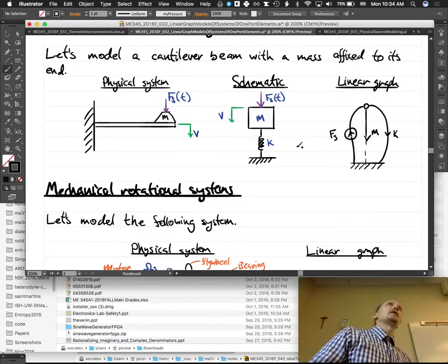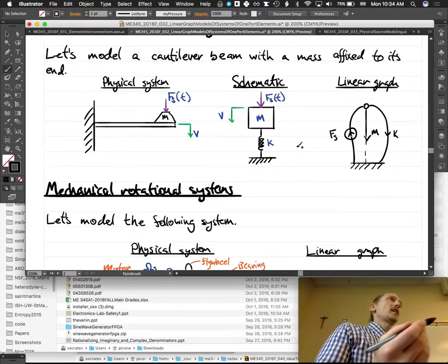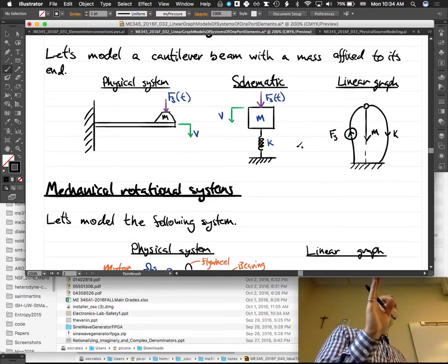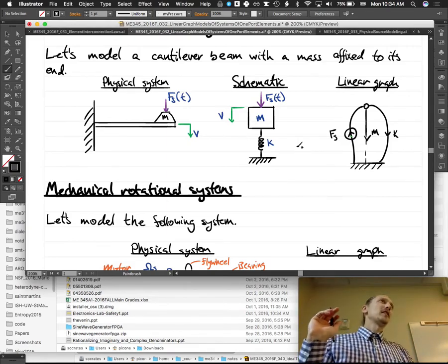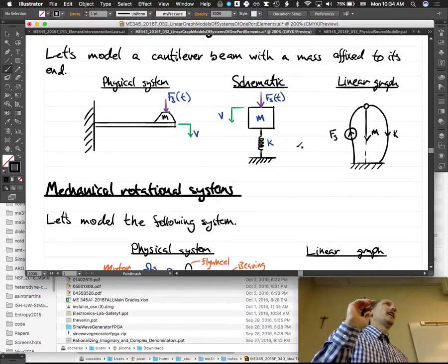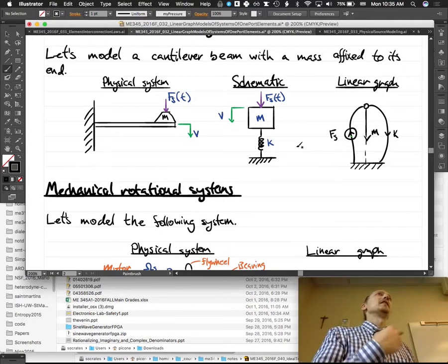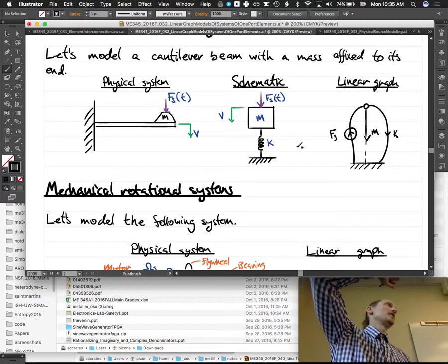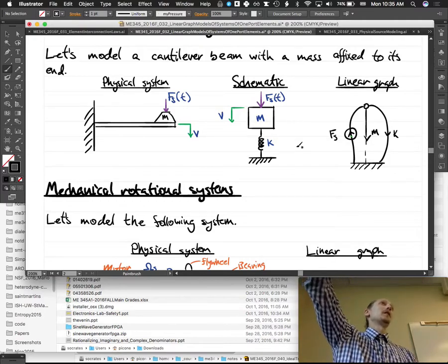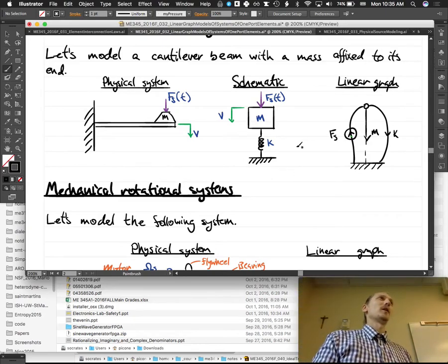So yeah, the sign convention is there, just like when you drew free body diagrams. Depending on your professor, you assumed that all the forces were, for instance, in the positive x direction. I know sometimes they don't teach you that. I personally always teach that all the forces are assumed to be going in the positive coordinate direction. And then if they come out negative, they're going the opposite direction of the coordinate system. So you always know what it is.